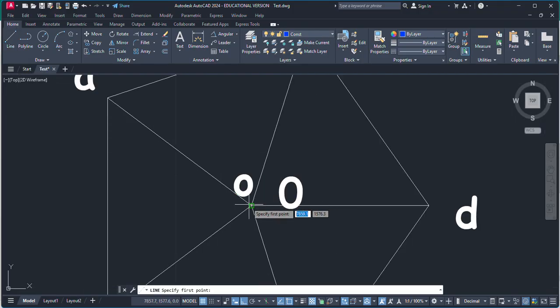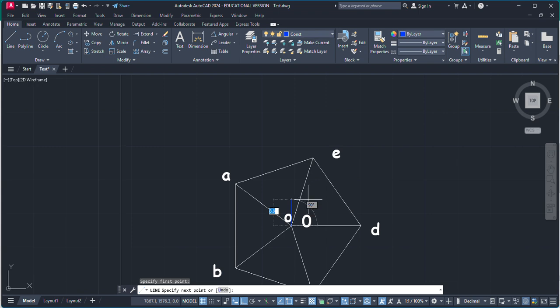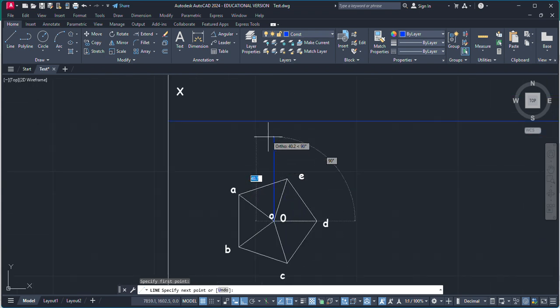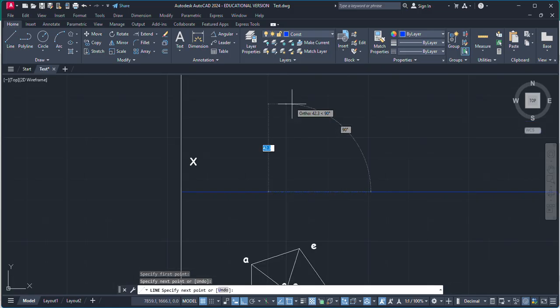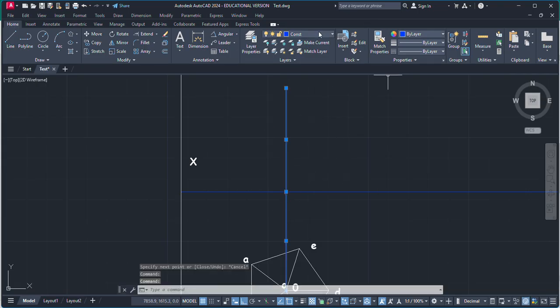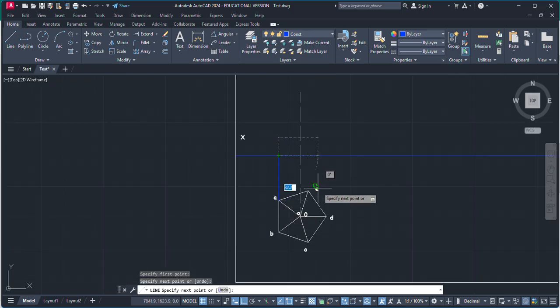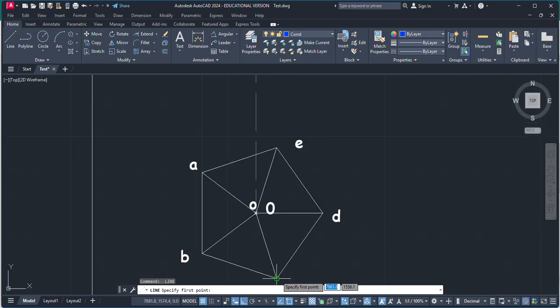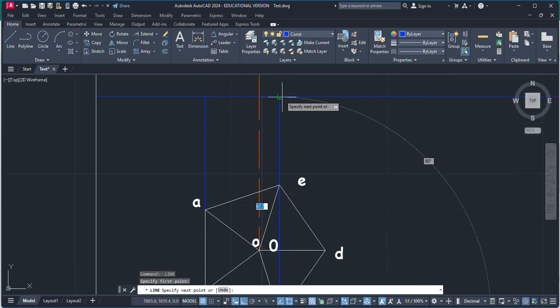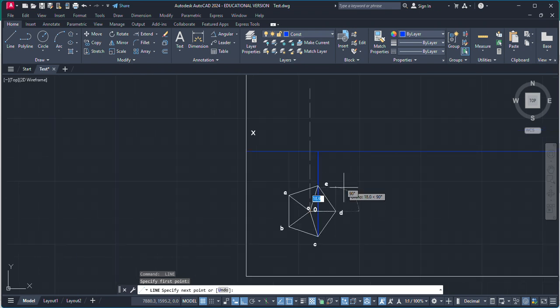Again, I have to provide the axial height, or from this top view, we have to create our front view. So from the center, I'm going to create this one, and from this reference line, the height of this pentagonal pyramid is 50 mm. Now, just going to change this line to axis. This is a central axis. Now draw the construction lines to complete the front view. Both points, C and E, lie on this vertical line, and this one stays individual.